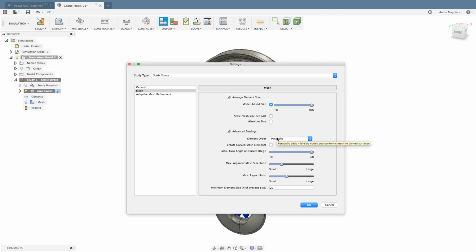It's because there's typically a little bit of troubleshooting that you'll do as you're working through this. So for first pass analyses, I like to keep it as simple as humanly possible. Use the dumbest, coarsest mesh. Your results will be garbage, and we're not going to take those as final results at all. But it is something that we want to get back fast so that we can continue to iterate on the simulation setup, because there's a lot of that that happens.